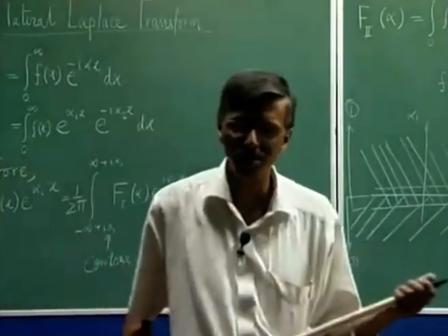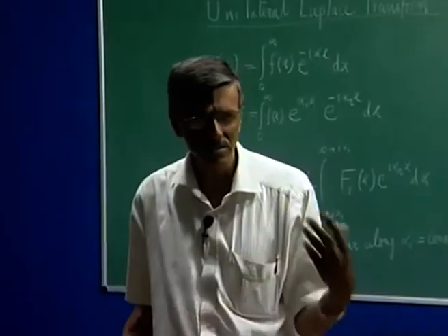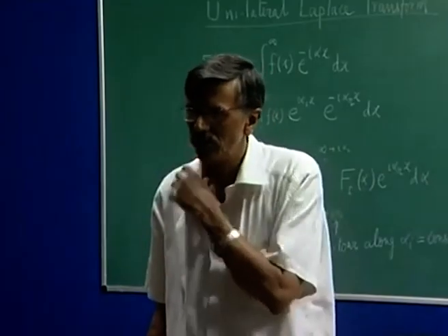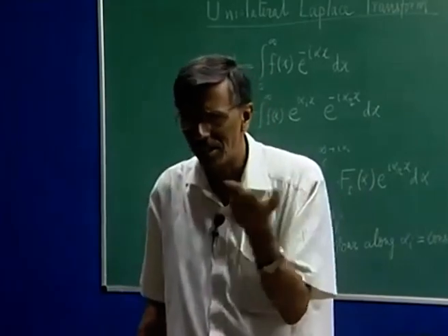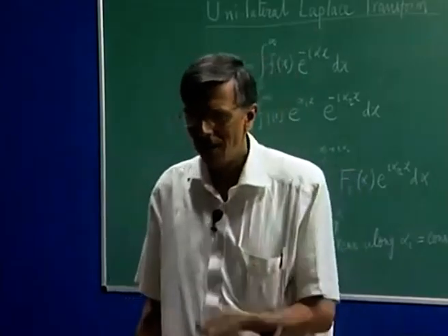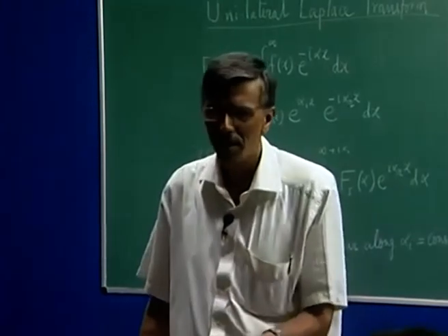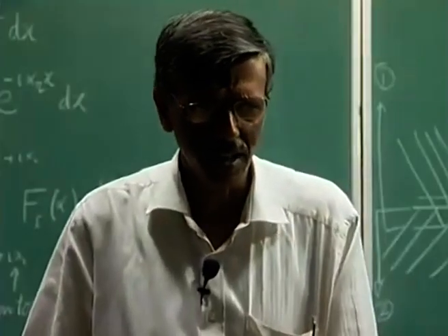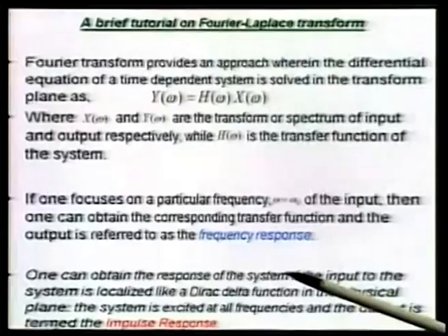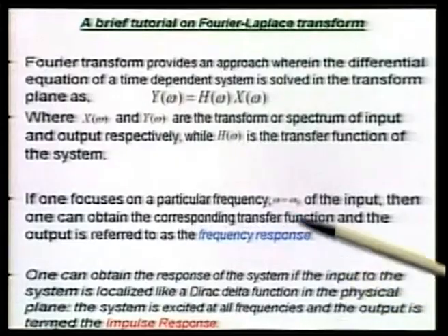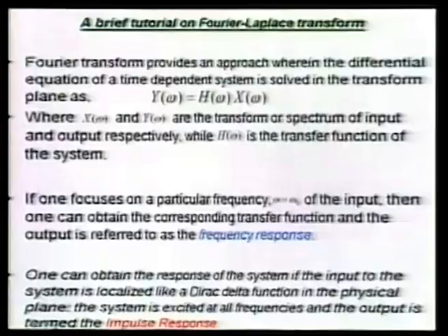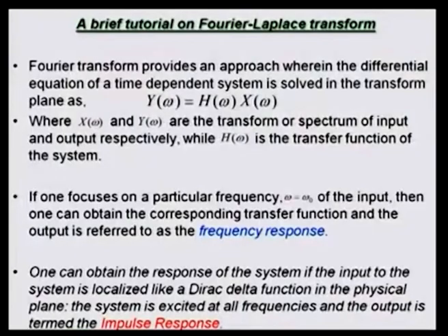You have done some experiments in your lab, etc., in dynamical systems or vibration analysis. You have done it in a structural dynamics course, right. You vibrate the system at a fixed frequency. You have a shaker, and then you excite the structure with the shaker, and then you measure the response. That is what is called the frequency response, because you are focusing upon a particular frequency, the frequency of the shaker.